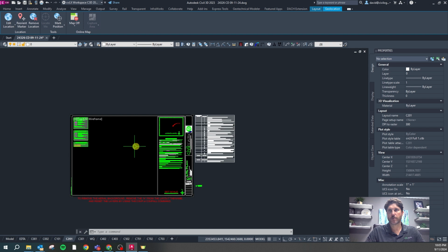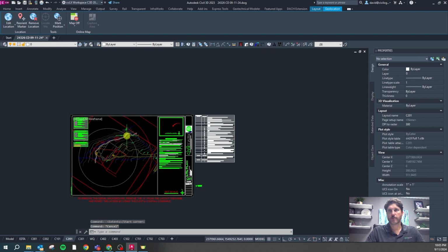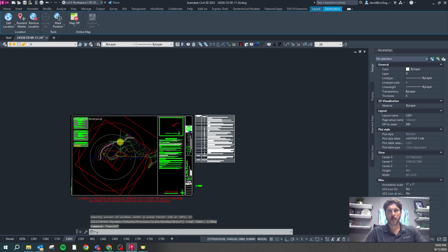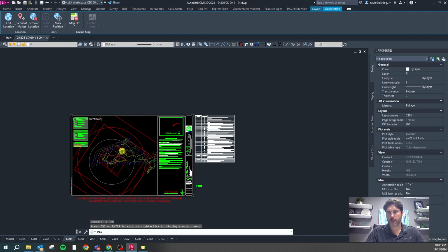And then up here is our project. So I'm going to zoom in over here. I'm just going to take a guess that this drawing is going to be a 20 scale. I can set that by Z for zoom, and then 1/20 XP. And that looks pretty good. If we did a 10, it probably wouldn't even fit on the page. So a 20 is probably appropriate.